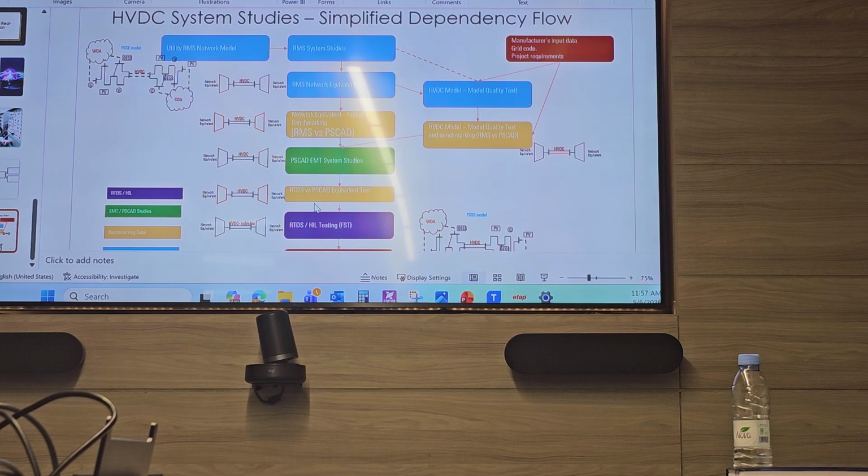Yeah. For relay protection, we will do commissioning. Normally, you will do testing at the factory to confirm the relay operates with these values. You say, okay, good, and send it to site. On site, you will inject the real settings and again do commissioning. But in this case, commissioning will be almost only connecting the wiring, and when you want to confirm that this works, it has to be connected to the network. That's the only thing.